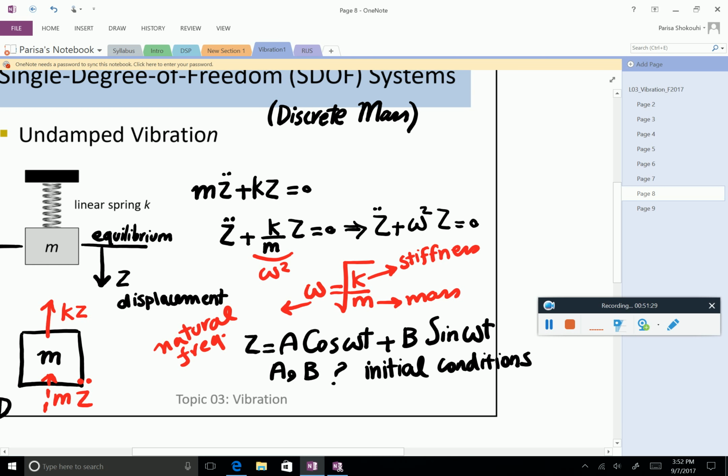Now, let's look at this a little bit more. It's very simple, but what do you see here? The natural frequency depends on the stiffness and mass density. Think about Jay's paper again. If you know the mass, and if you measure the frequency of the system, somehow magically you can get the elastic constant. It doesn't seem to be too magical, because you can even see in this small system the relationship between frequency and stiffness. So you see where this is going to go. Of course, this system has only one natural frequency. It's a very simple system.